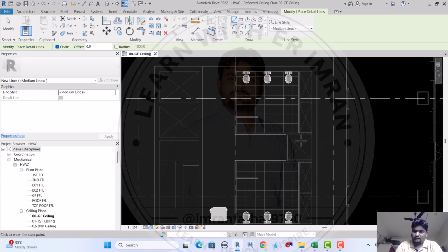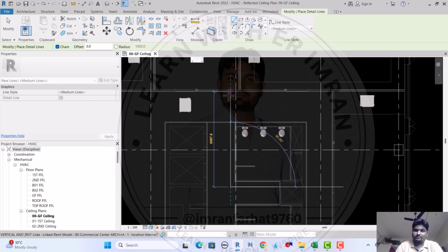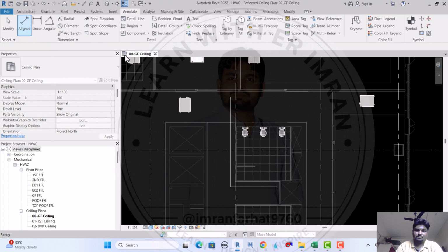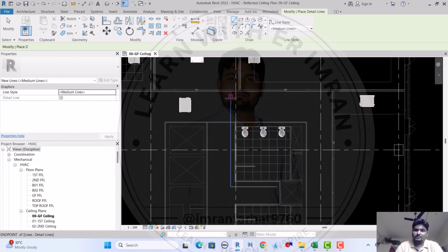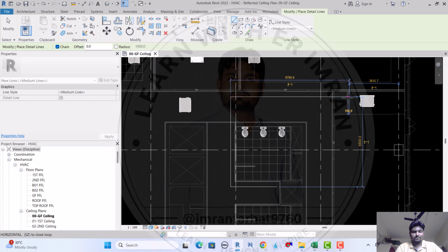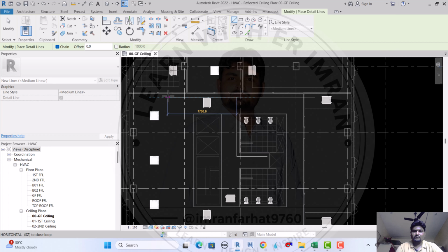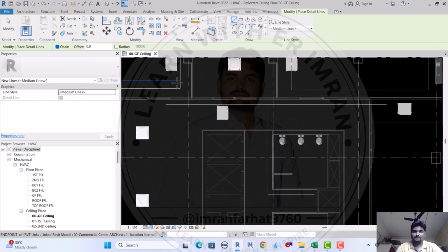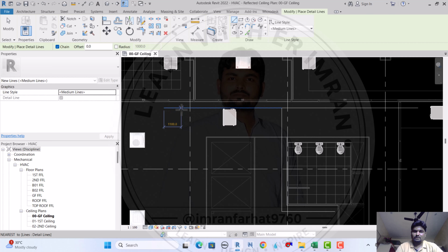So through this OTS our refrigerant pipe, liquid or gas, will come, because the outdoor unit is placed on the roof. From there it will come through this OTS, and suppose it will come here. After that it will go here. Remember that we will do one separate for indoor and common areas for the other outdoor unit. So it will come from here.